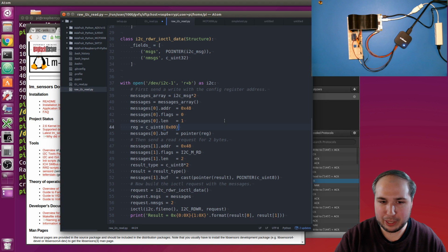And I think a smart way to do it, it's not necessarily the best way, but a smart way to do it is to write pure Python code where there's no C extension. It's just Python, and pure in the sense that I'm not relying on any libraries. I'm just using built-in Python stuff. So the C-types library is built in, IO control is built in. That's all I need to talk I2C. And so when I do that, then I can actually make this work with Python 3, because Python 3 also has the IO control library function. It also has C-types built into it. There's sometimes little differences in those libraries, but you can smooth those over in your Python code. I'm not actually building a C extension.